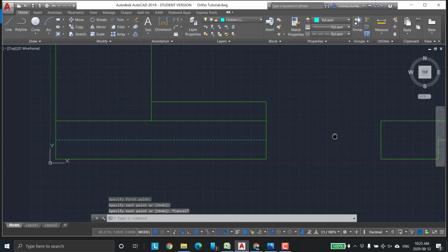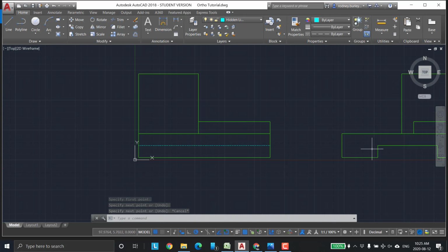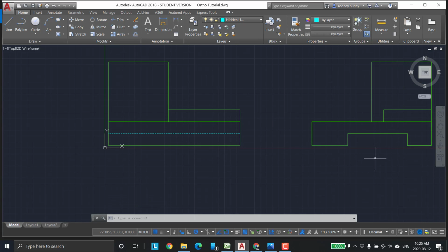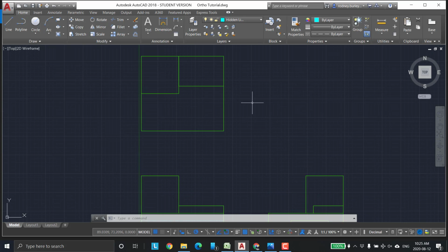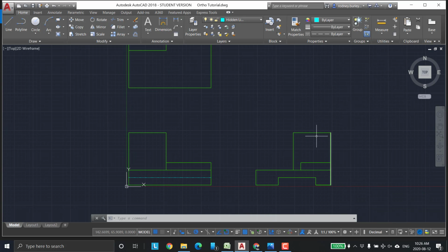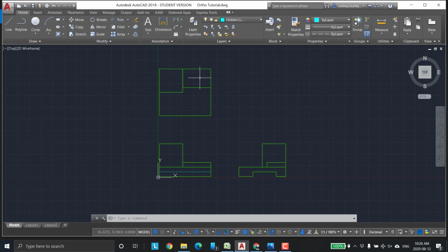And now you can see I've got a hidden line feature, and you can see it's exactly right. There's no other hidden lines on this layer, right? Because you wouldn't see this line, and you wouldn't see this line. This would be the only one you would see hidden running the right way through. Now the top, there would also be hidden lines here. No hidden lines here, just one hidden line here. And then this one here, the channel, you would see two hidden lines.